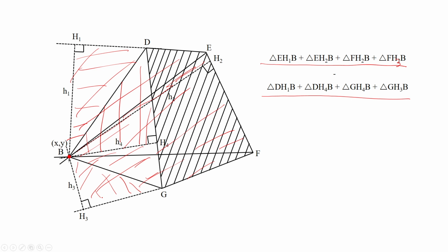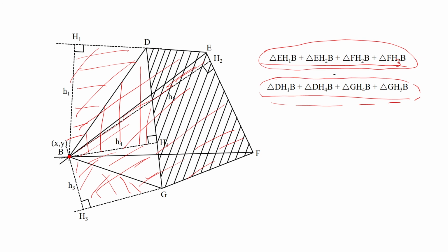So, in essence, in one kind of calculation we think that the positive load is applied over these triangles, which are all right angle triangles, and then negative load is applied on these triangles, which are again right angle triangles. We have already deduced the results for the loading of a right angle triangle on a point like this. And so, we extend those ideas that we have deduced in the previous lectures, and we use those results here and use this principle of superposition to find the deformation at this particular point B. So, that is the idea.